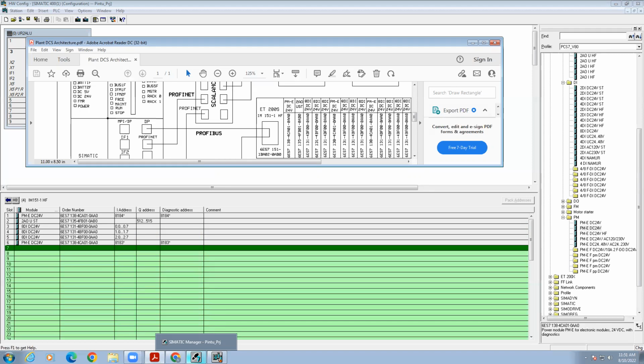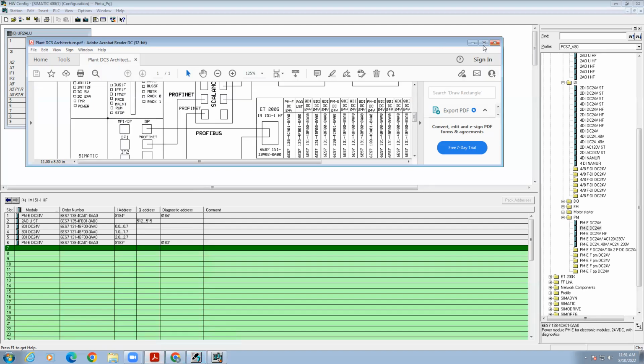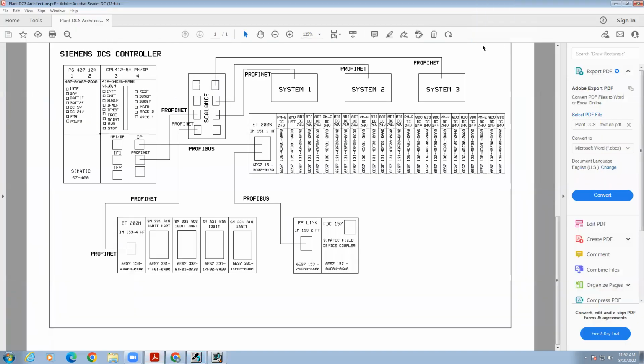Suppose you do the internal power supply with SMPS, then you don't need to add the power supply modules; you just add your IOs. Different power supplies and different commons are connected, right? It depends on how your architecture is. Now you can ask me, sir, who designed this architecture? Actually, we can't create this architecture. It's not in our hands.